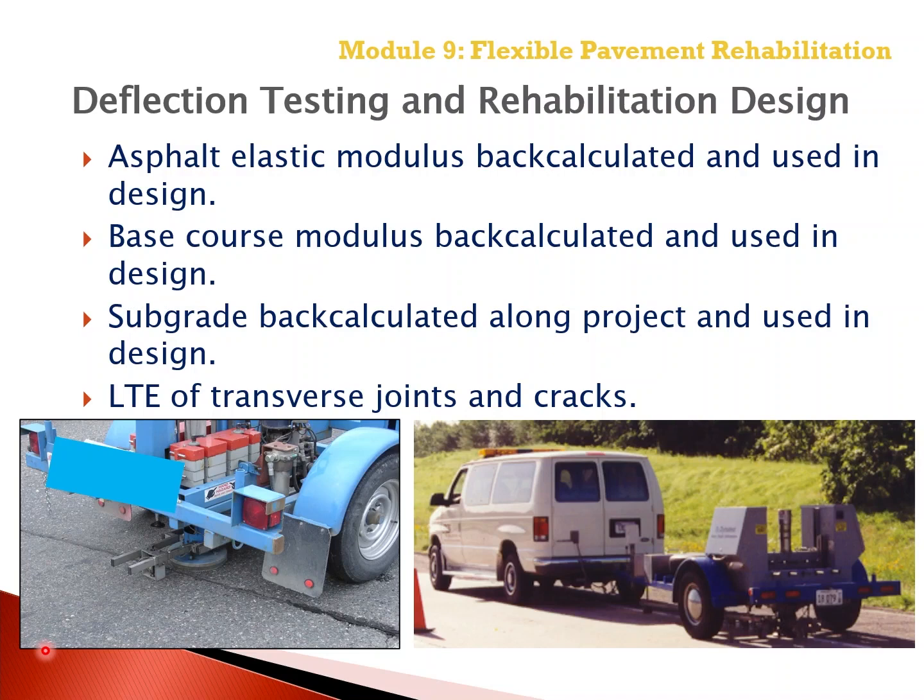Another important use of deflection testing is to measure and determine the load transfer efficiency of transverse joints and or cracks, specifically transverse cracks in existing flexible pavements. In addition, it can also be used to define the load transfer efficiency in underlying jointed plain concrete pavements in terms of the transverse joints in those concrete pavements.